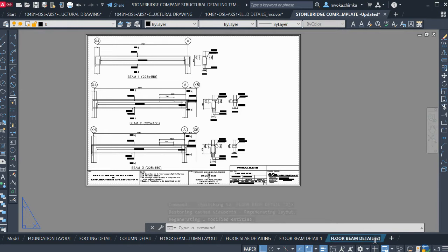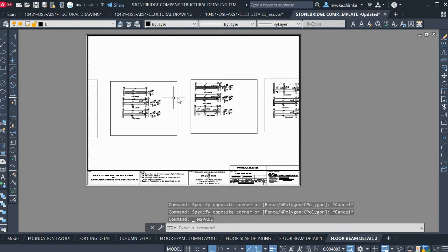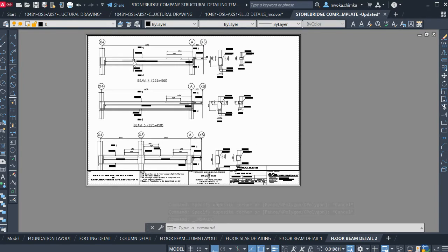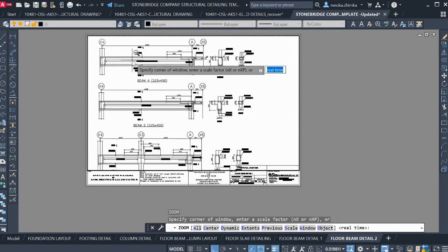So just change this, remove these brackets and make it beam detail two, and then click at this place and locate the next drawing to bring out here. Use a scale to position the drawing. Z enter, 1 all over 50, SP enter.